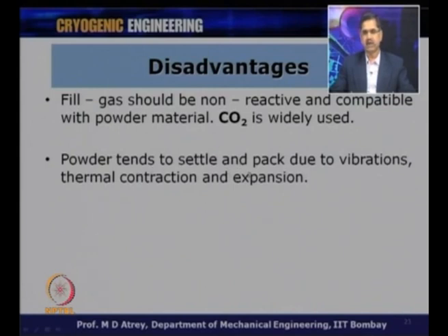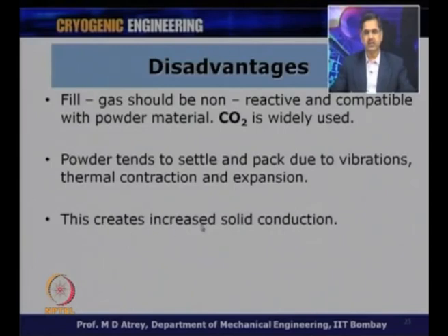So, the powder tends to settle and pack due to vibrations, and then you have thermal contraction and sometimes expansion also because of heating effects. This creates increased solid conduction, and therefore this has to be considered in the usage of such insulation.